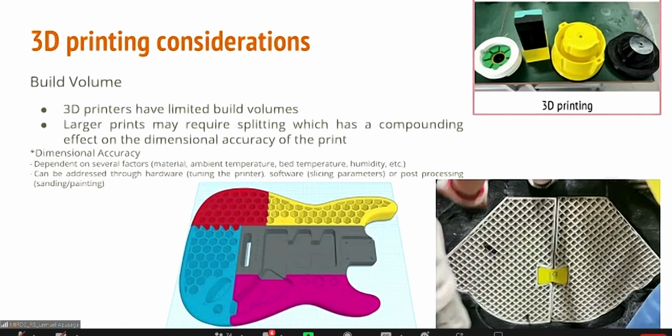Of course, the issue about this is that as you segment it into more parts, there's going to be error in the mating, because it's not as accurate as building the whole part as one whole part. If you make it as an assembly of smaller parts, you introduce errors in the dimensions, so you also have to be careful about that. Once you assemble your part, make sure to still measure the part that you make and make sure that it is still correct.